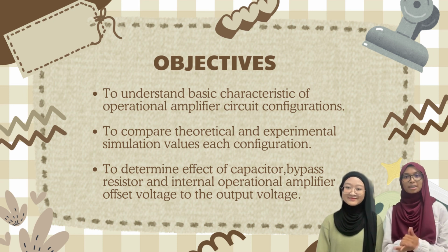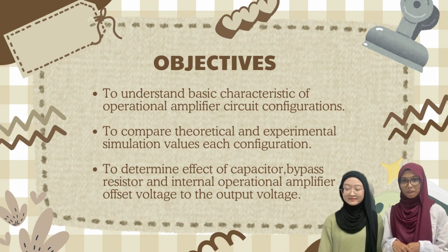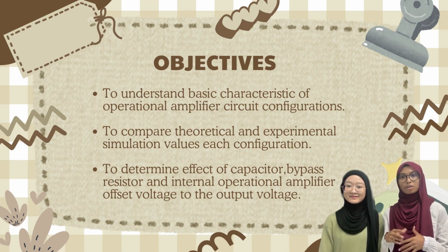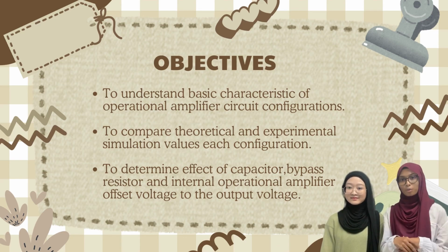The differentiator and integrator circuits are mathematical processes that the op-amp can execute. Besides, we also examine the function of the big feedback resistor in preventing DC drift and saturation for the integrator, while the differentiator's ability is to transform a triangle wave into a square wave output.